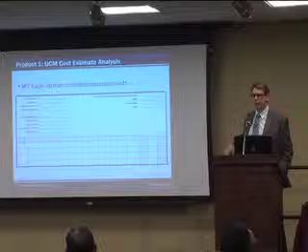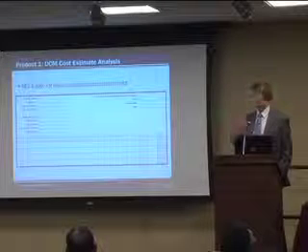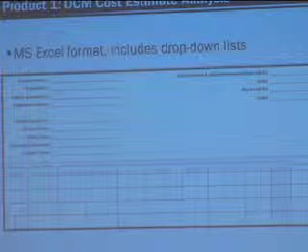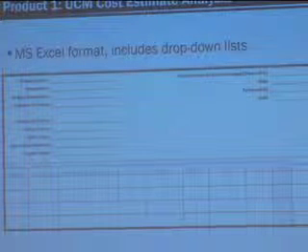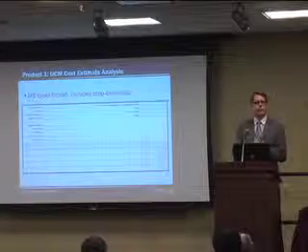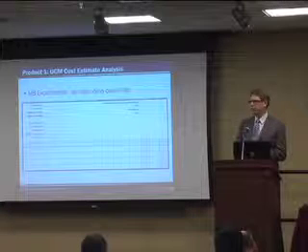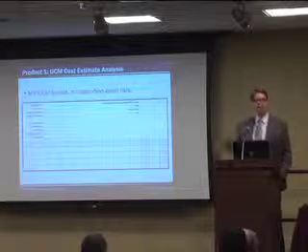In that first matrix that I showed you, we had another column about a cost estimate. We wanted to keep track of cost estimates for each utility conflict, but then we had some meetings where we went to the state DOTs in Arkansas, California, and also Texas, and we quickly noticed there was a lot of confusion about this cost estimate. What are we really talking about? Is this the initial estimate to remove the conflict, or is this the estimate of what it's going to cost the DOT? So we figured out, okay, we can't really deal with the cost information in one column. We had to expand the whole thing a little bit.